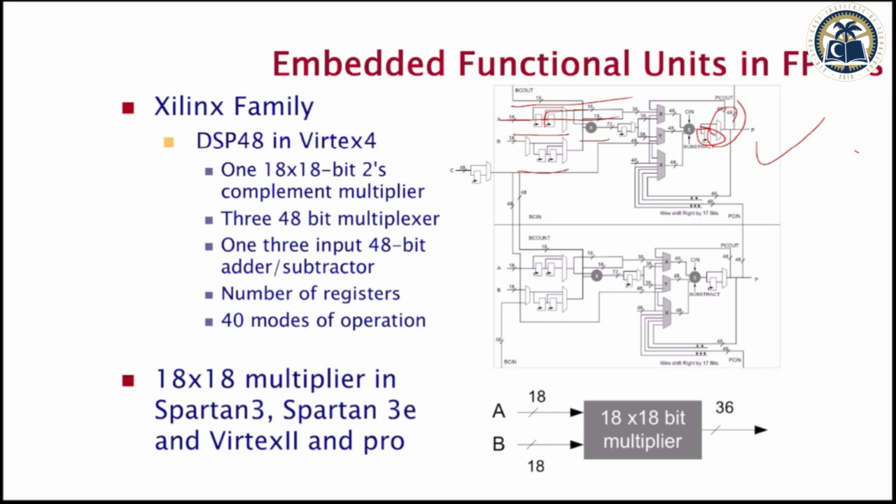That's why this is an FPGA, because it gives you all conceivable options to use a multiplier and an adder. A MAC. So it says, oh, you are using a MAC. A MAC means that somehow you need to take your multiplication result and feed it directly to the adder. There is a way.